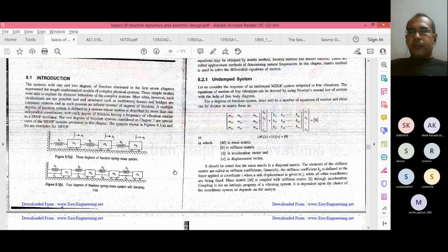So you have 7 masses and 7 stiffnesses in your building, right? That is what you need to first calculate if you want to do it manually for the dynamic analysis of the building. Clear? So in Excel, you need to first calculate the masses and then the stiffness of all stories of your building. That is the first step, and this is called the mathematical representation of your building. Software also follows this model only.